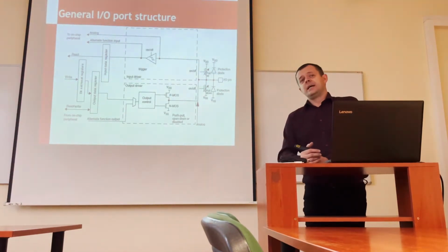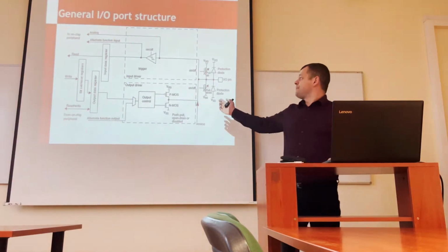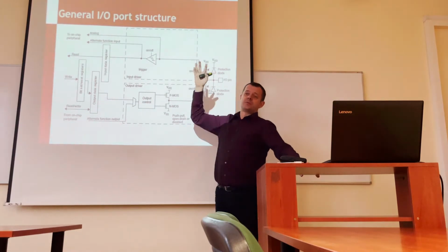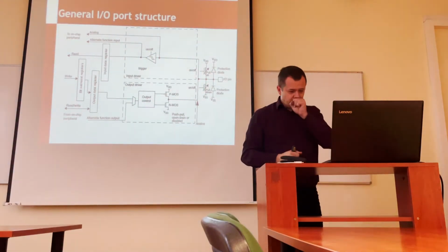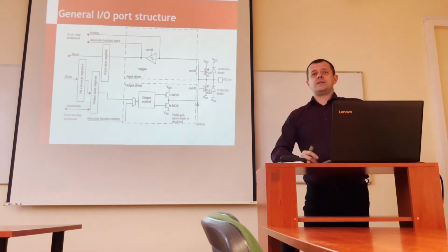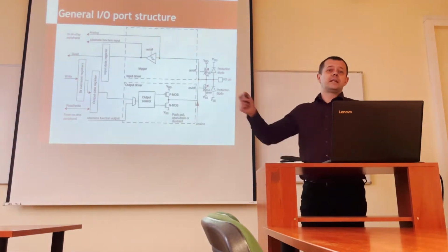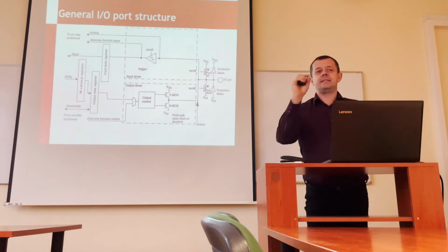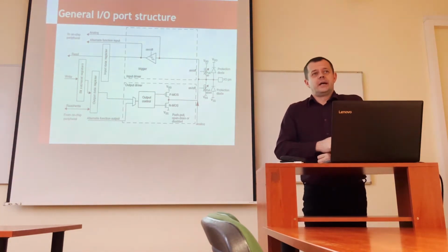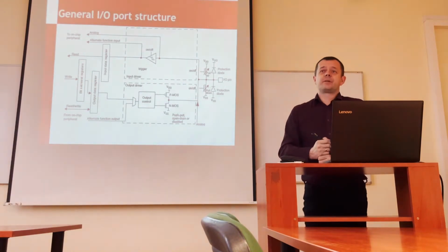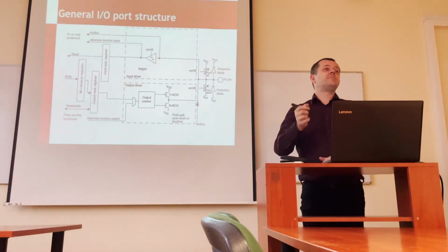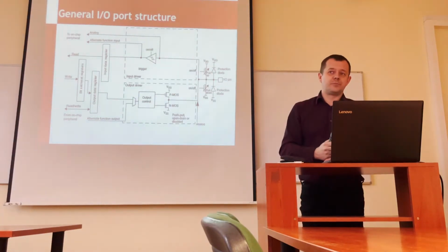What does it mean? It means that you can connect to an output port almost any number of inputs. That's not that obvious, so I'm stressing this out, because in the classic TTL logic, which we talked about a bit during the introduction to microcontrollers, there was a limit of about 10 inputs to one output.